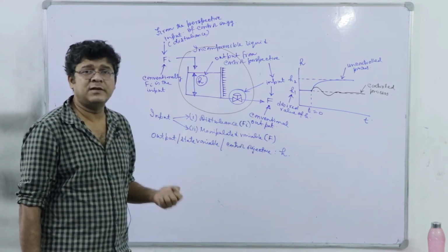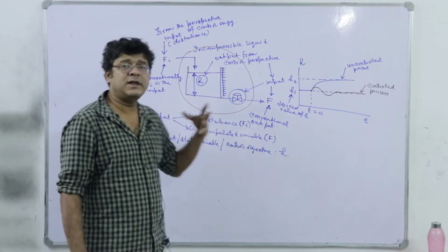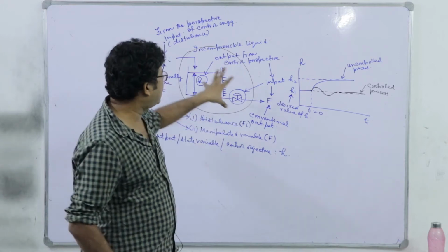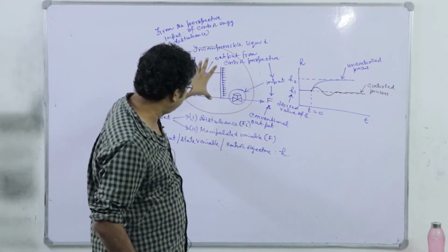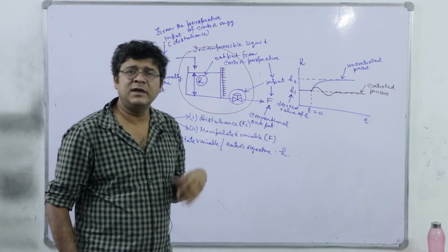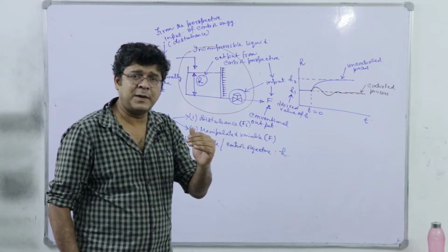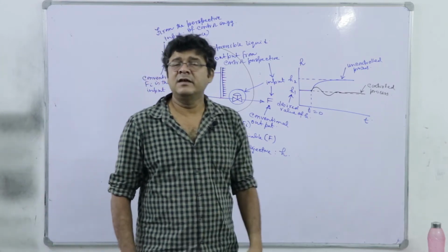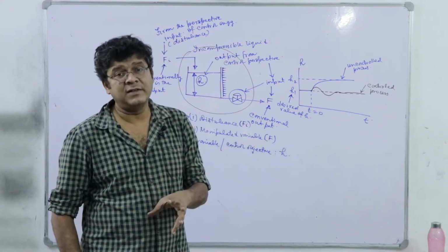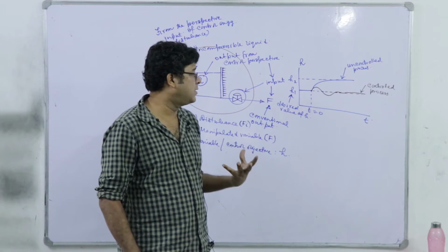Based on this idea, we can have disturbances, and we also have a manipulated variable. Without any manipulated variable, it is not possible to control a system. So we must have a manipulated variable, and if we don't have any disturbance, then in process control, in a typical chemical plant, there is no need to control the system. Once what we suspect as disturbance is always at its steady state, there is no need to control the device. However, in some situations, not here, we can still have the requirement of controlling it.